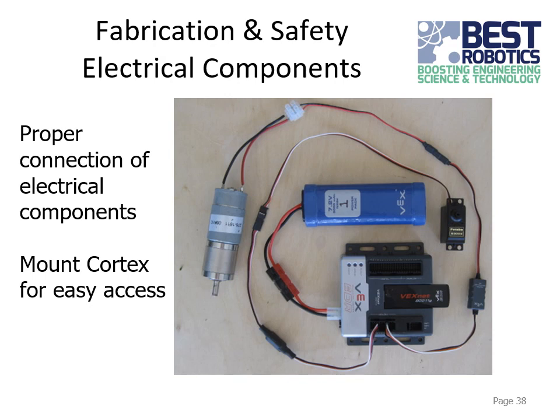Okay, on to some electrical components. Make sure everything is properly connected, first of all. I'd say make sure polarities are matched up correctly. So that means red to red, black to black, that sort of thing. Also, make sure everything is secure in its connection too, so it's not going to fall apart when it shakes a little bit or have an intermittent connection.